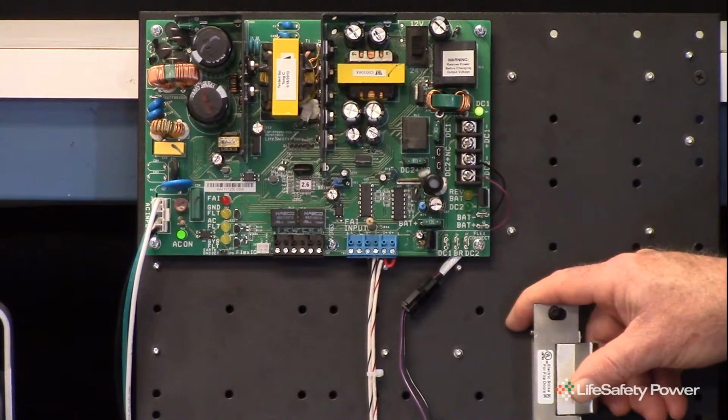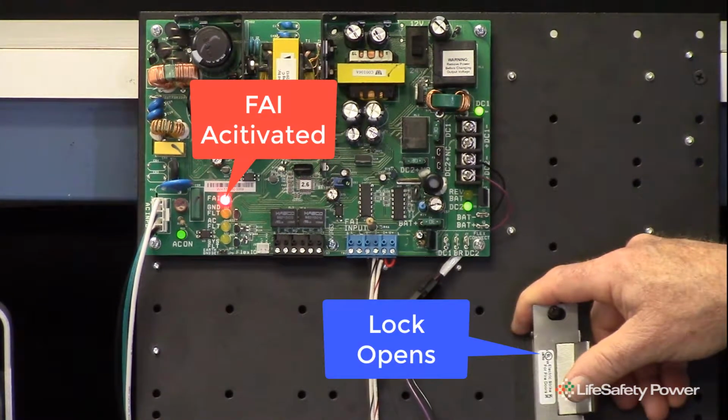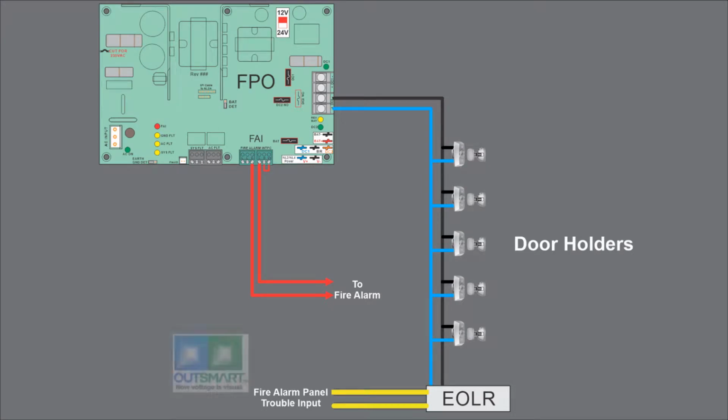This is a fail-safe strike. It is now locked with no power applied. If I activate the FPO, you can see that now the lock opens up. Locked again.